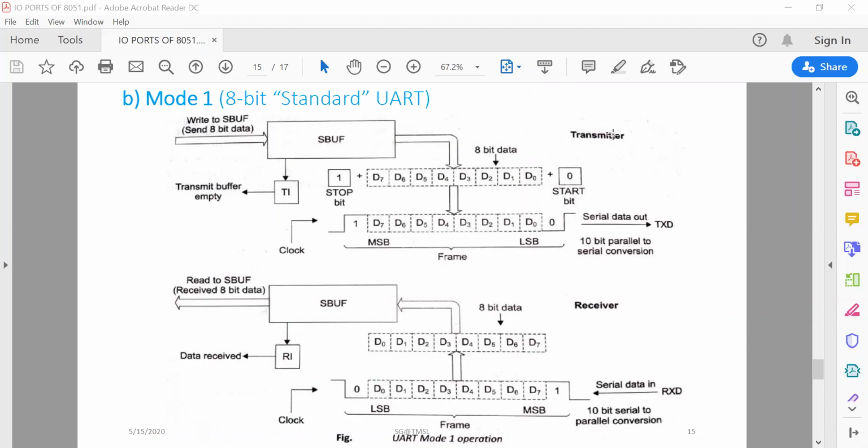Serial buffer is empty, and a new byte can be written to it to start the next transmission. If a new byte is written to the SBUF before TI is 1, or high, the untransmitted part of the previous byte will be lost. So it should be noted that the microcontroller sets the TI flag when it completes the byte transfer, whereas it must be cleared by the programmer after the next byte is loaded into the serial buffer.